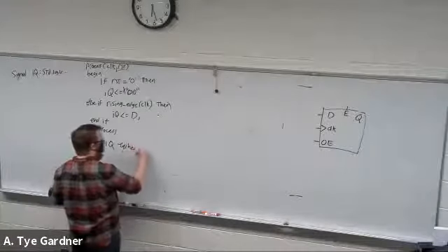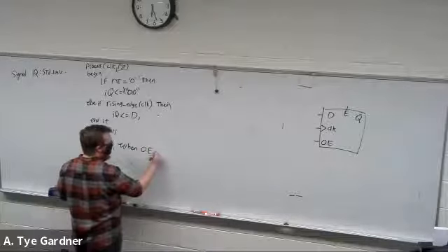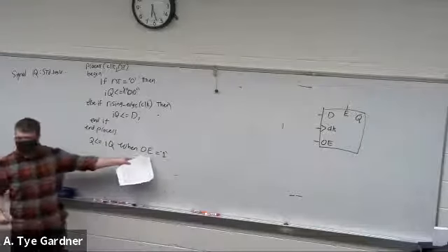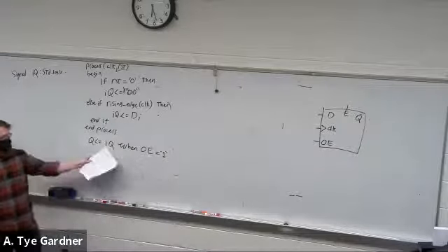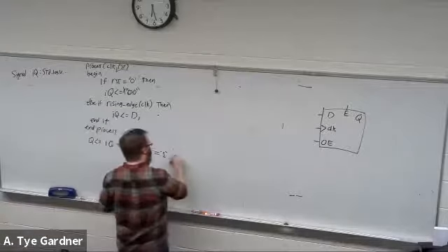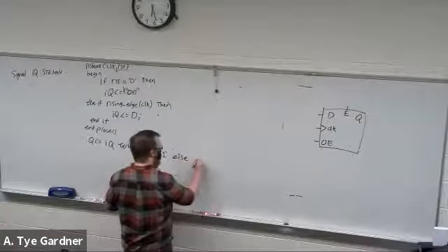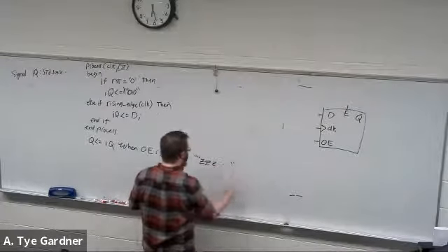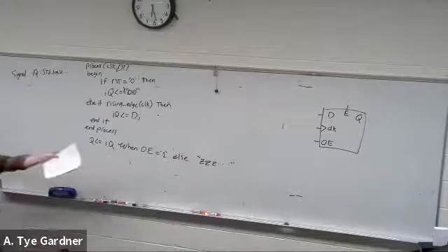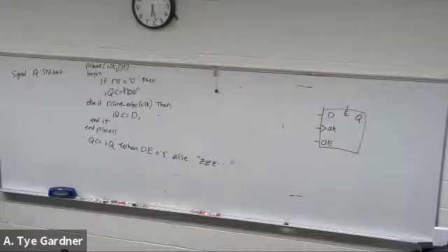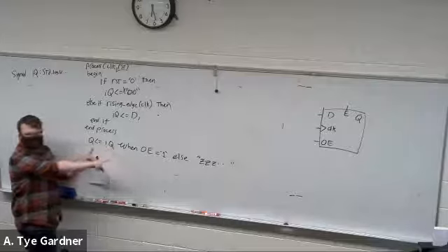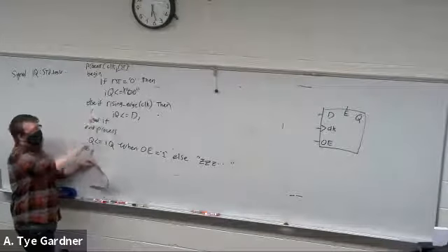when output enable is equal to 1. So if I'm output enabled, then Q gets that. Otherwise, so else, Z. And I have to have 8 Z's because it's 8 bits. Now notice, this statement is okay to be outside of a process. The ifs have to be inside, this can be outside.